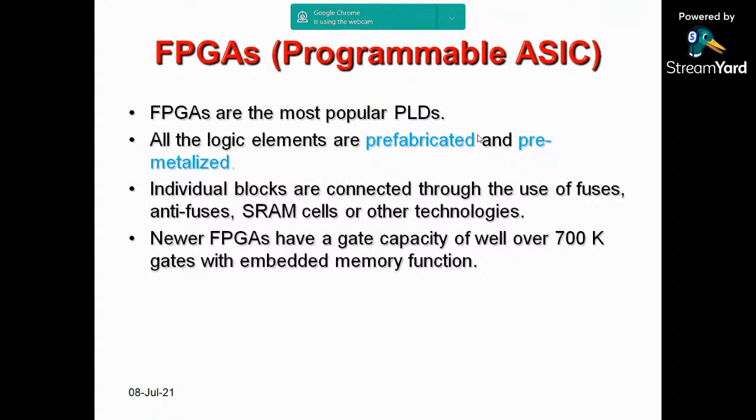What are PAL and PLA? They are nothing but an AND plane and an OR plane being manufactured. The only thing is you need to blow the fuse, or form the fuse between the two lines, to realize your function. But they're all one-time programmable. Either you make it or break it, the function will be realized, but they're all one-time programmable.